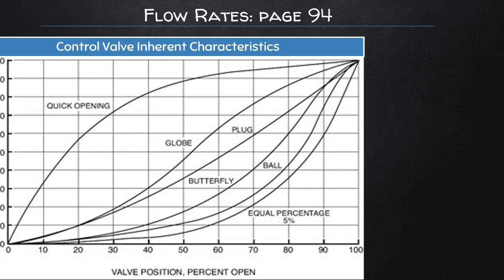So this would then obviously be the preferred type of valve to be using for that situation, a solid that needs to pass through the valve, rather than a plug valve, because the plug can be quite a small entrance, and the plug itself can also get in the way of the flow. But all these choices really have to do more with the process dynamics and control philosophy that you want to follow, where the type of valve characteristic is chosen in such a way that the process control can be achieved efficiently.